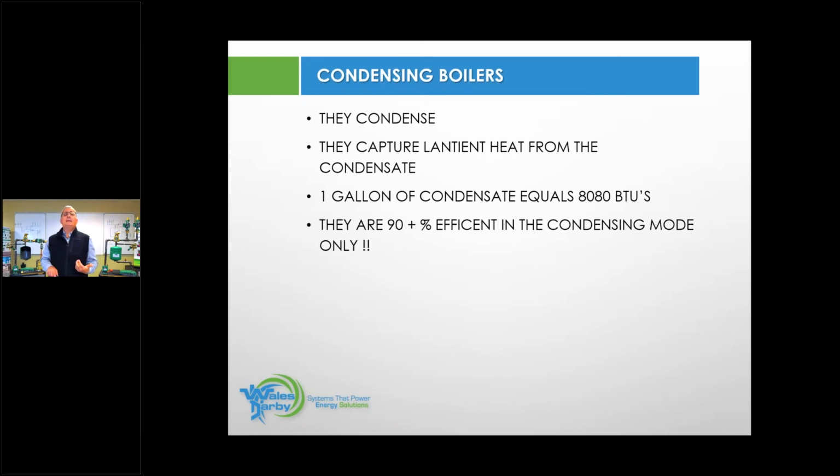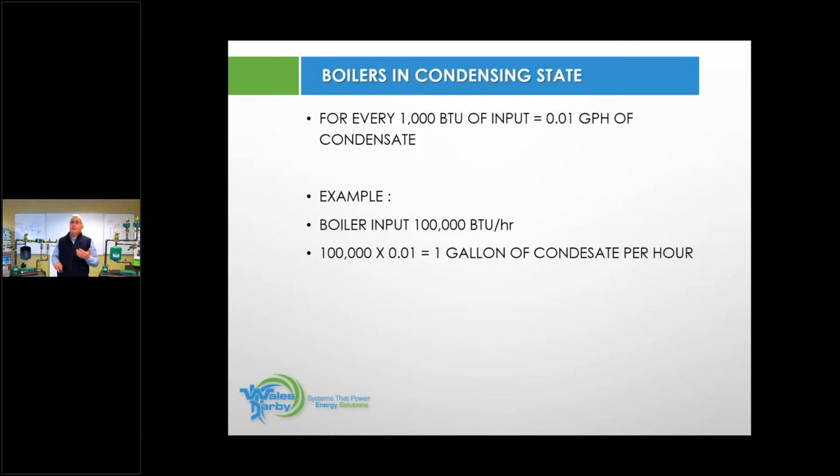So if we don't make a condensing boiler condense, you guys are better salesmen than me. You sold a high-end boiler with really neat controls, looks great, and it's going to perform just like standard cast iron. So if we're going that route, let's make them condense. That's why we went through this exercise today. All right. So there's the